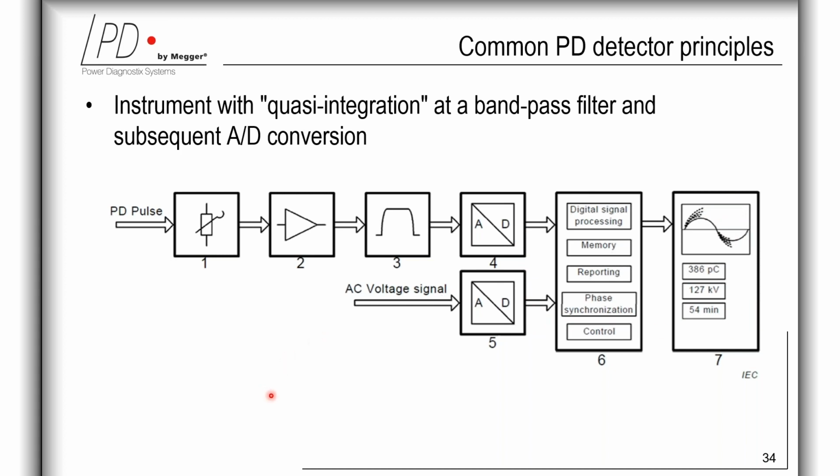All electrical methods we mentioned do have in common that they are using bandpass filters to select the frequency band. In this context, the bandpass characteristic of the coupling circuits needs to be considered as well, since this signal contains complex filters of higher order, and their behavior influences the impulse properties of the PD signal.